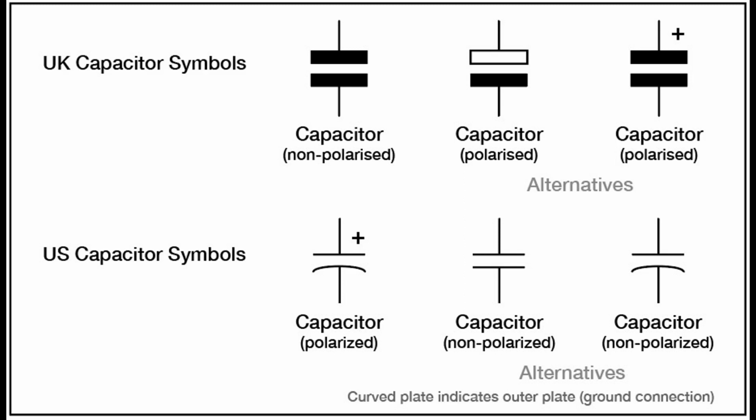Lighting ballasts. Electrolytic capacitors are employed in lighting ballasts, which are used in fluorescent lamps and high-intensity discharge (HID) lamps. They help regulate the current and provide stable voltage for proper lamp operation. Power factor correction (PFC) circuits. PFC circuits are used in power electronics to improve the power factor and efficiency of electrical systems.